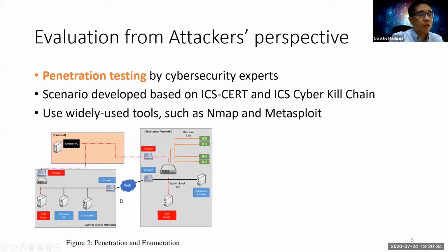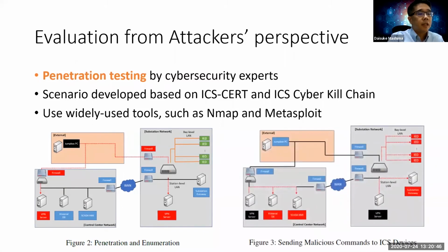After successfully penetrating into the system, the next step for the attacker is to collect information in the system by enumerating the devices or services running there. In the next phase, the attacker's goal is to inject a malicious control command into smart grid devices, in particular IEDs. IEDs are basically the communication endpoint on the cyber side, and they are connected to the physical power grid components. The attacker may inject a malicious command via a SCADA HMI workstation, just like the Ukraine power plant attack in 2015, or directly inject a command to the substation system. To emulate these kinds of attack scenarios, we utilize widely used cybersecurity tools such as Nmap and Metasploit.